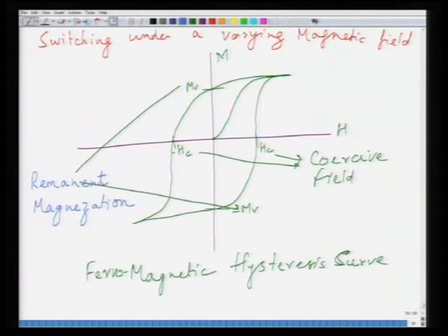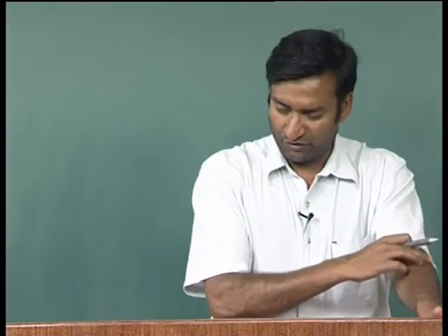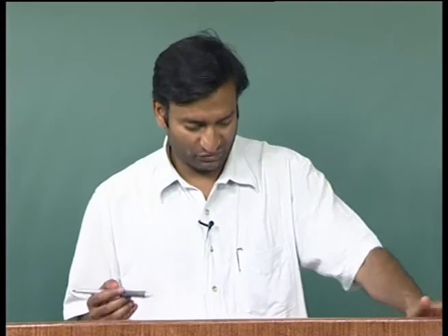And the energy which is dissipated now, because you have hysteresis, which means you have some energy dissipated, this energy dissipation defines the nature of a ferromagnet. This term is not used for ferroelectrics in general, but for ferromagnetic materials you have this term which defines whether you have a soft magnet or a hard magnet, and we look at it in a while.